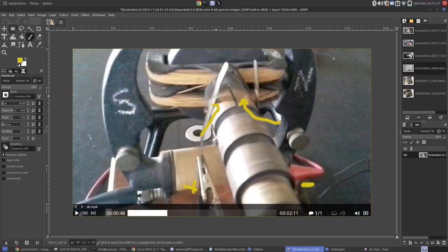So basically, the natural alternating current that we have in the coil of wire, we switch it to being a direct current by having, every time we rotate the commutator, a different brush touching. So the two effects cancel each other out and we get that sort of pulsed DC current. We're going to see that for both generators and motors, brushes and a commutator are key.